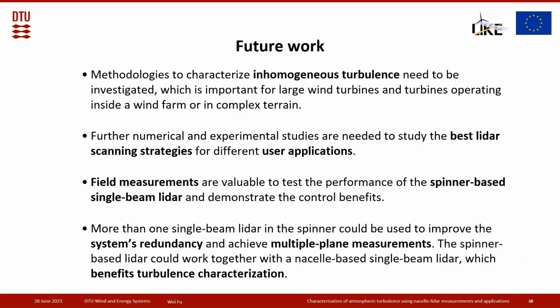So for future work, I would say the most relevant one is that our methodology assumes that the turbulence is homogeneous. So we need to investigate methods to characterize inhomogeneous turbulence, which is getting more and more important for turbines with large rotor spans or those operating inside wakes or in complex terrain.